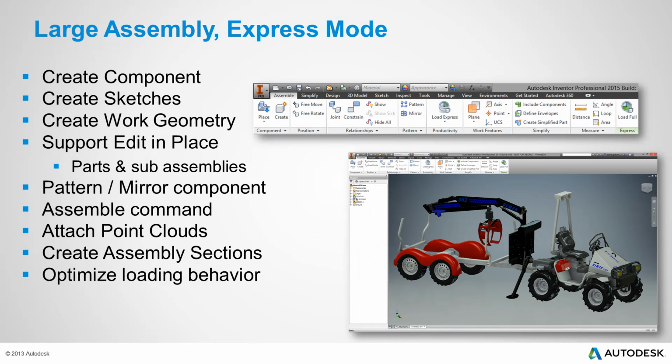Okay, last thing we're going to take a look at today are the changes which have been made to Express Mode, the Express Mode tools when working in large assemblies. We have enhanced this greatly from 2014 to 2015. And we've included the capability now to create components, sketches, work geometry. You can edit in place.